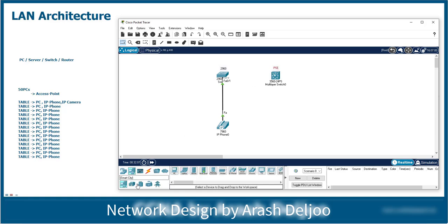When you install an IP phone, this is the IP phone, and if you connect this device to the PSE without the need to connect the IP phone with the power adapter to the AC power, the IP phone turns on. As you can see, now the IP phone is working. Why? Because the PSE, this switch, can now supply power to this device.